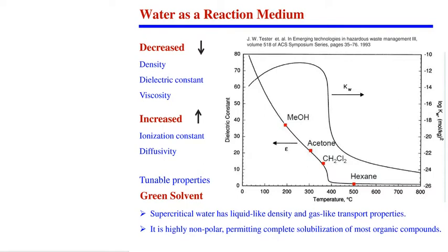Let me give you an example with the switchgrass to bioethanol, how it is made. If you have a switchgrass, that is basically lignocellulose material. If you think of it like a compound, it has cellulose, hemicellulose and lignin. Hydrothermal pre-treatment I did in one of my research between 180 to 220 degrees C, and then the pre-treated biomass goes for fermentation to make ethanol.